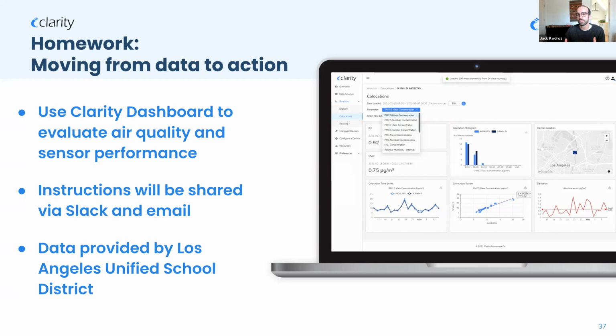In addition, with the data you have from co-location, you can also use that data to evaluate the sensor. So the important difference is co-location is physically putting them together to generate the data you will use to do other things. Calibration is one of the things you can use with the data from co-location, where you correct the sensor. Now, not all calibrations come from co-location.